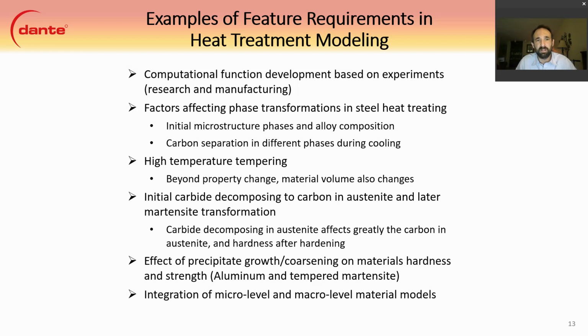We also need to look at high temperature tempering, beyond just a property change, such as the hardness, ductility, strength. There's also material volume changes which occur particularly at higher temperatures. You don't so much see the volume changes at low temperature, so this is more of a high temperature phenomenon. There's also the stress relaxation which occurs.